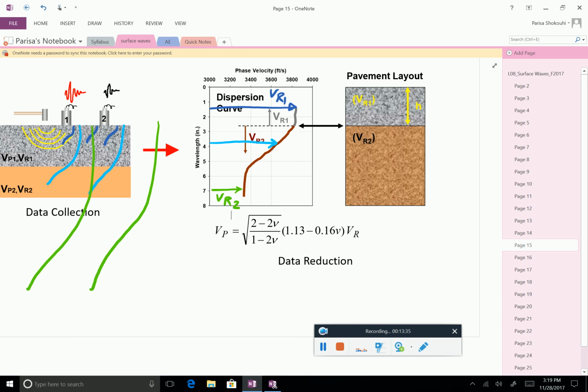Then you would do surface wave. You just confine your frequencies such that you are looking at the wavelengths which are within that layer, and the velocity would be the velocity of the material. It becomes complicated when you have multiple layers and you don't actually know how many layers and how the velocities are different. Because as you can see here, in this region, the velocity is a combination of the velocities.